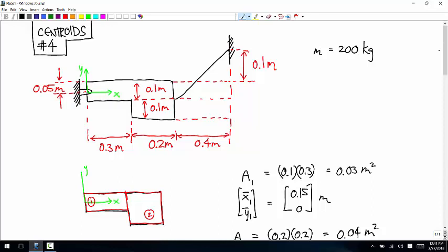And we know the magnitude is going to be T. So we want a unit vector that points in that direction. So if we can come up with a non-unit vector, just any vector that goes in that direction, then we can normalize it, divide by its magnitude, then multiply by T, and then that's our force vector.